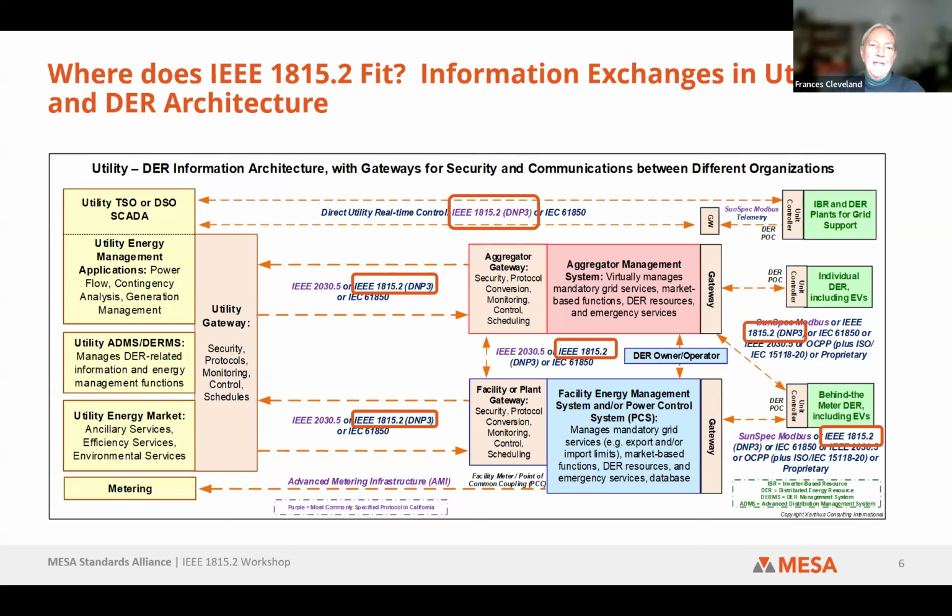That's really the debating point right now, as to which one should be used. And I think it might depend upon what the circumstances are. If it's just essentially, for instance, the SCADA interactions with the IBR, you might go ahead and try SAv6, even if it's not fully tested, because you'll only have one or two of them, just a few of them. You don't need the full AMP capability. But if you're going to be running lots, 50, 100 plants that are going to use DNP3, I would suggest sticking with SAv5 for the time being.